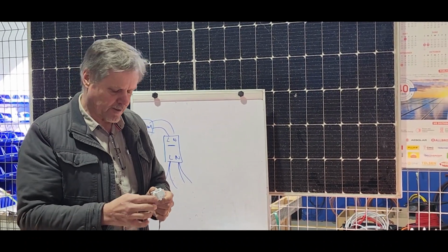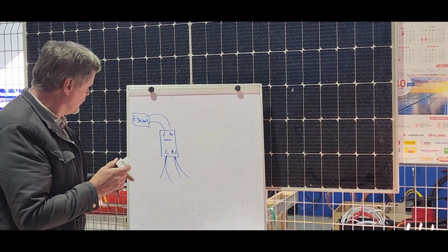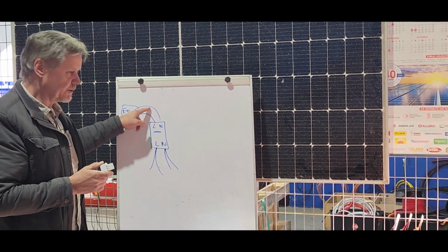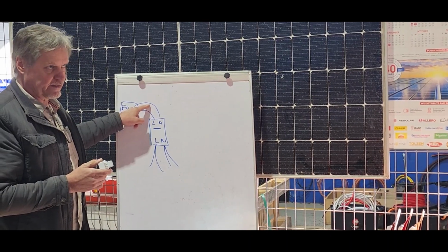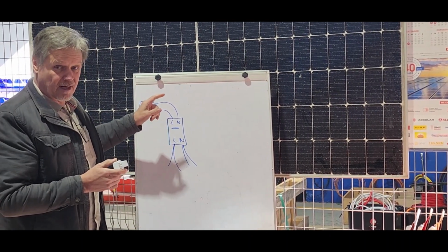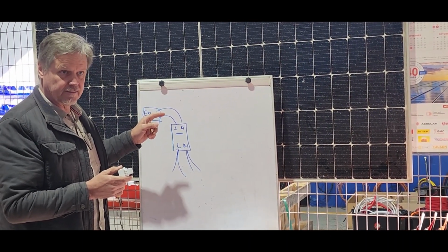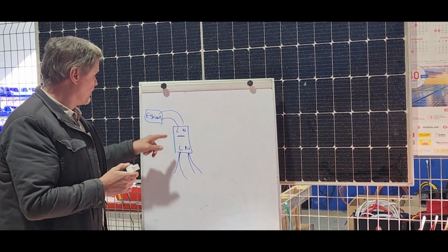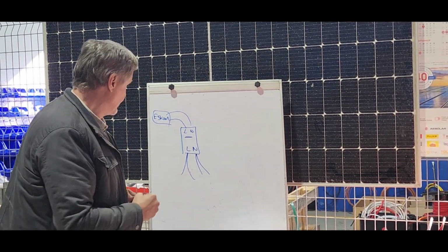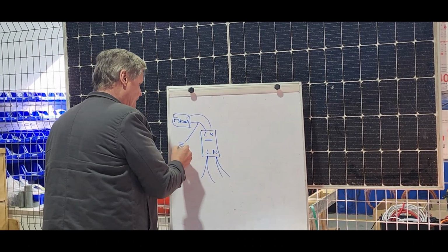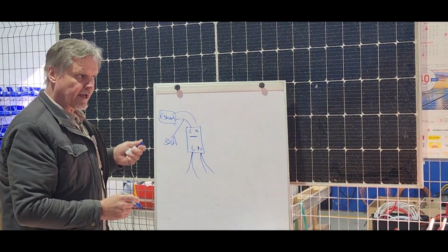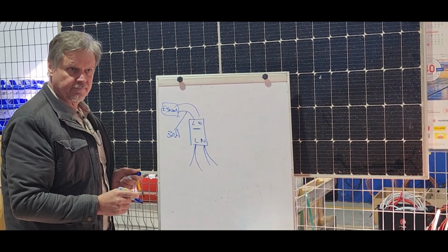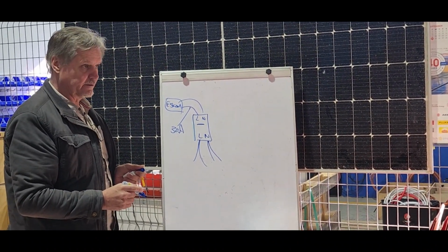Okay, right. So which cable do you clip this on? There's live and there's neutral. Which one do you use? Live. Yes. Must I use the live or can I use the neutral as well? Maybe a question is, let's say there is 30 amps running in the live, how many amps are running in the neutral? 30 amps. 30 amps, you agree?